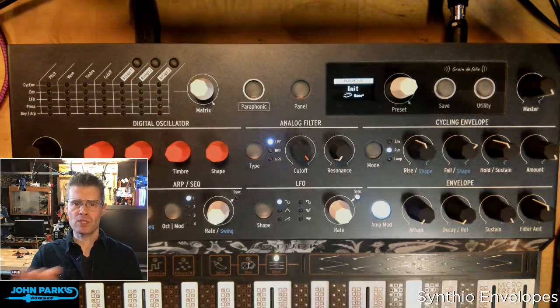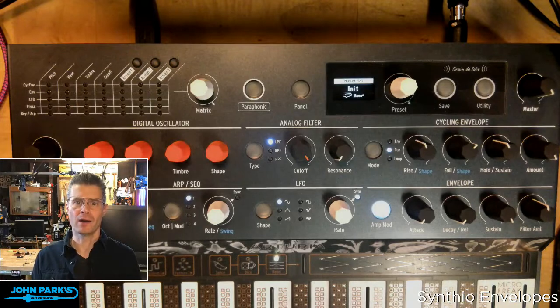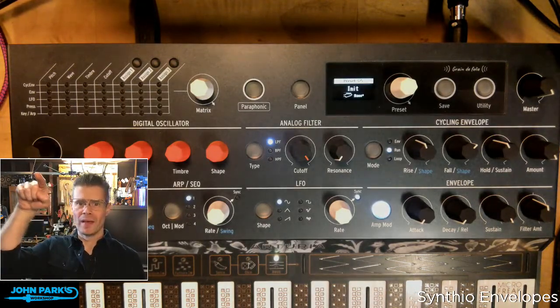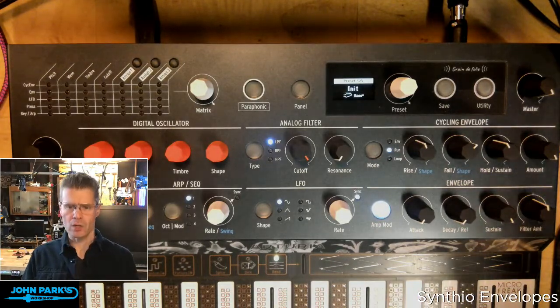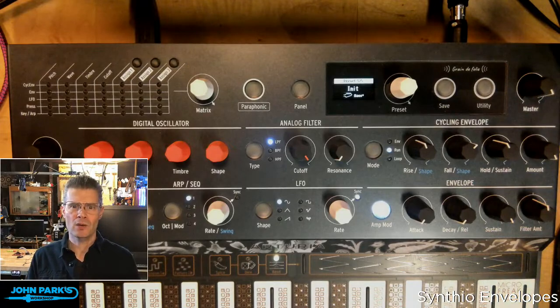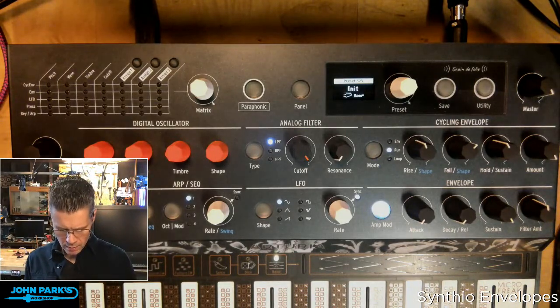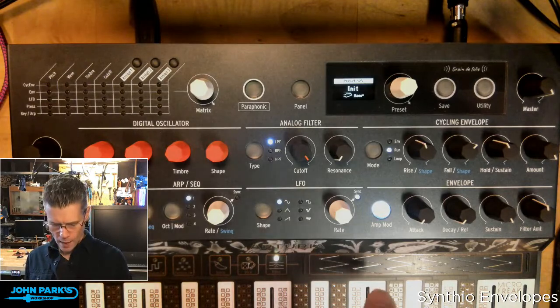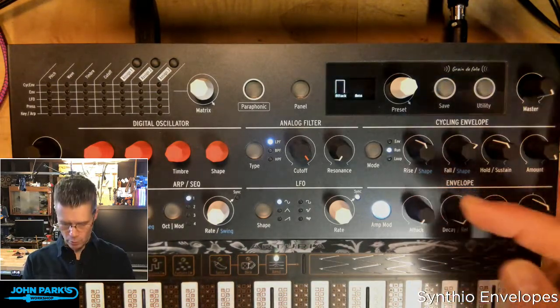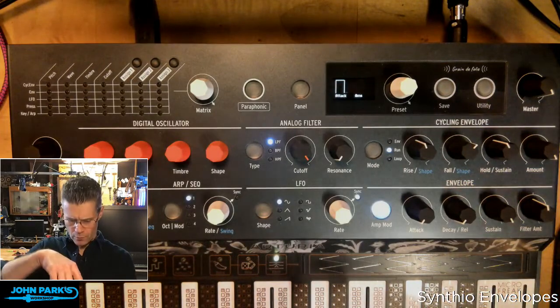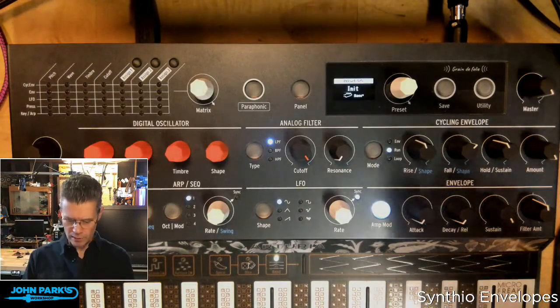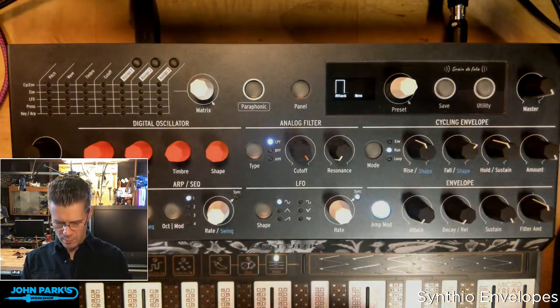The main thing we're talking about with envelopes is essentially a sound going on and off, a sound when we press a key being audible and then no longer being audible. So these are sometimes called attenuators, volume attenuators. Voltage controlled amplifier is a term you'll hear. It's not really an amplifier, but it's attenuating the level of the sound that we hear from nothing to full sound, using shapes of curves in between. So to demonstrate, this is a really square shaped envelope here. When I press it, it goes to full volume, stays there while I hold it, and when I release it, it drops immediately. So you can see by that shape how that happens.